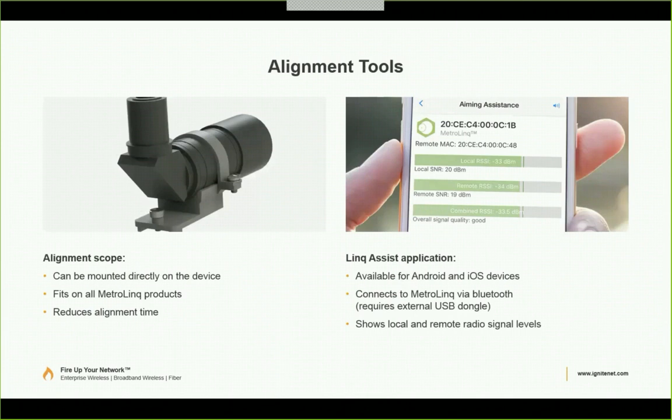So somebody asked the question, what is the max distance for point-to-point and point-to-multipoint on 60 gigahertz? So for point-to-point, the max distance that we recommend is 1.5 kilometers. You can actually get much farther if you're in a dry climate. However, 1.5 is what we recommend. For point-to-multipoint, we recommend about 1 kilometer if you're using the high-gain client to the Omni unit or the beamforming sector.